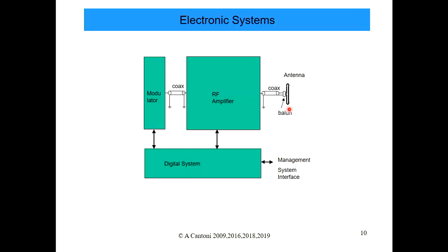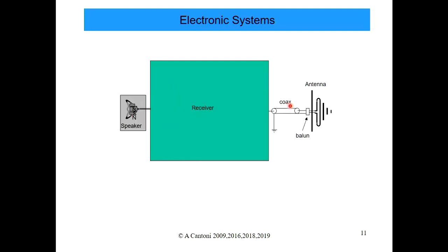It can't be represented as a lumped element, but we can make a model for it, and that's the key thing. When we make a model for it, we've got a VI relationship at this port, something that for every voltage tells us what the current's going to be. Then we can use that model in circuit theory, even though the actual element doesn't meet any of the criteria for circuit theory. But we have a model.